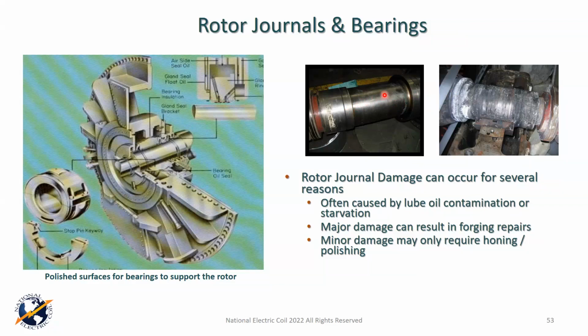And as you're changing out bearings or doing a rewind, you should be checking the journals and the oil seals, hydrogen seals, making sure everything's in check. A lot of bearing failures, the biggest probable cause is oil contamination. And most good maintenance programs have a very good program for monitoring the oil and filtering it and taking care of it or replacing it.